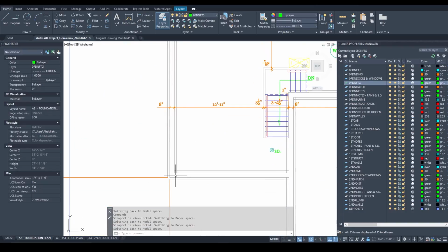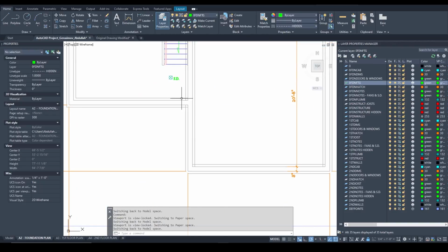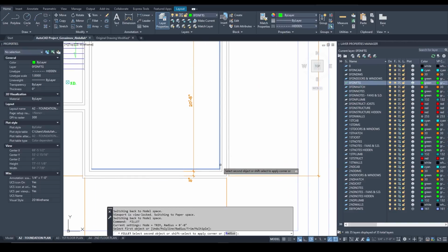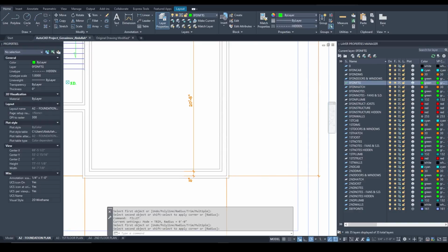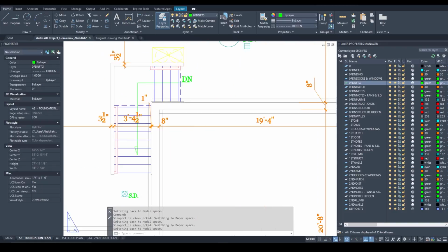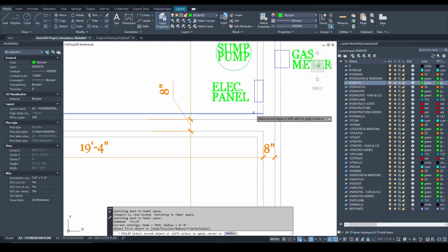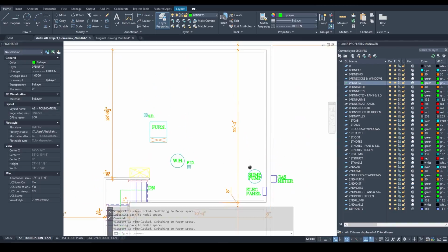First, let's go around and trim and or fillet the corners of our newly created lines, and then we can fix the layer type to which they are assigned. Again, if you press spacebar often enough, that should make your life very easy, and you shouldn't spend too much time dreading how many lines you have to create or trim.